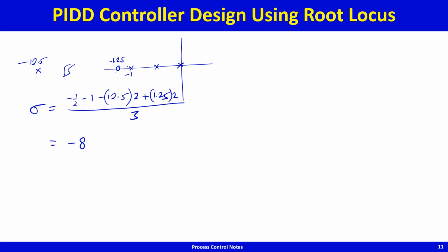So the asymptote is somewhere quite far away, somewhere over here. And you've got the asymptotes at minus 60 and plus 60. So yeah, you'll get the root locus like this. There will be a breakpoint, but then it must go towards the asymptote. So actually you will have something like this. That's what the root locus would look like. Quite curved.